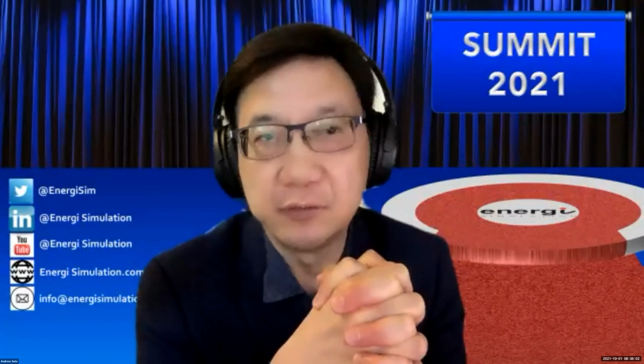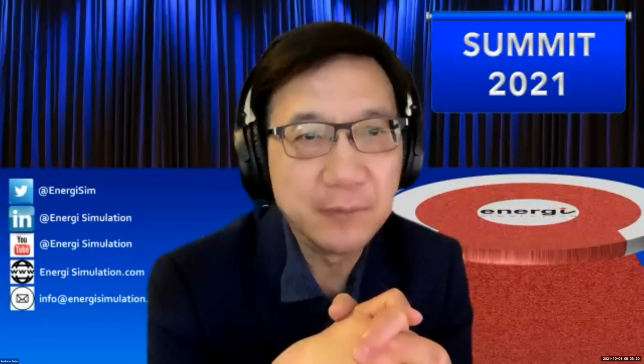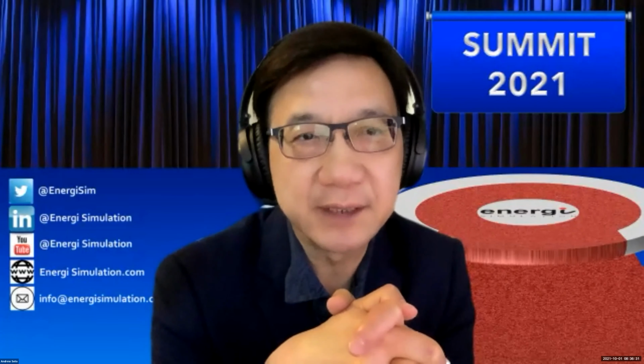Question from Dr. Russell Johns from Penn State University. Thanks, Rick, for an excellent talk, as usual. Caprock integrity is one of the important issues to store CO2, but another important issue for storage in an aquifer is likely regional groundwater flow. Regional flow could take CO2 away, either as a separate phase or dissolved in water to a distant outcrop. How might this leak-off influence the safety factors, and are you considering this?